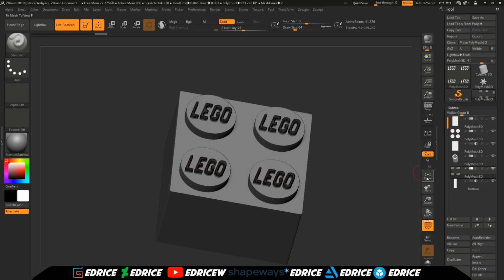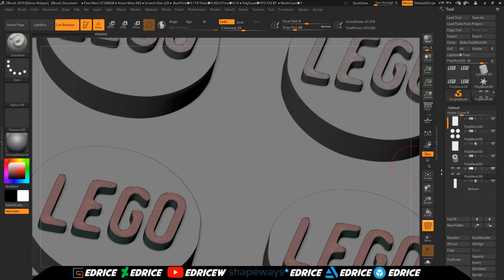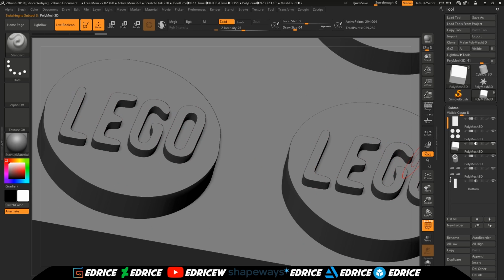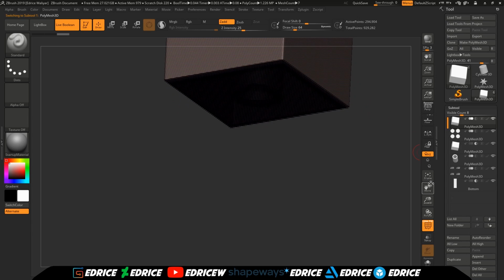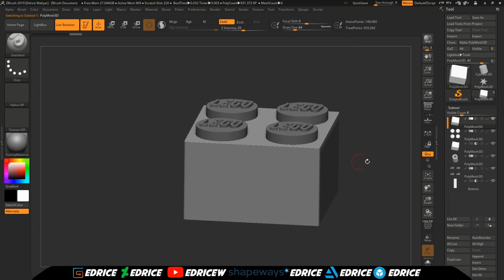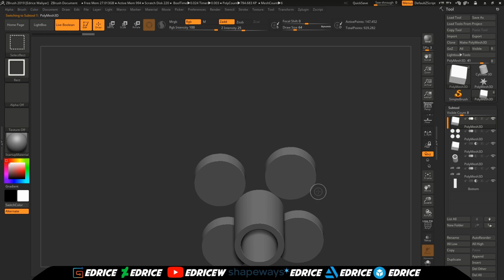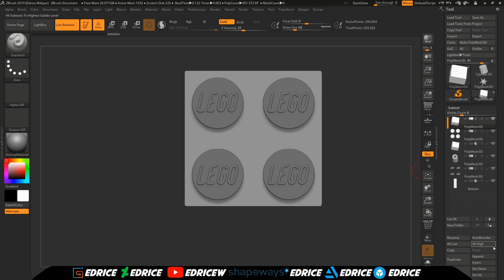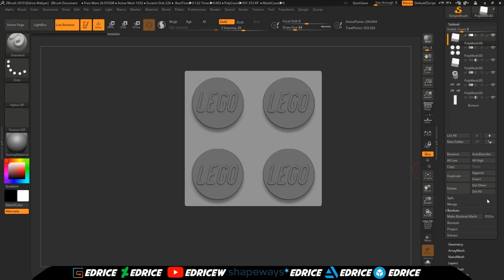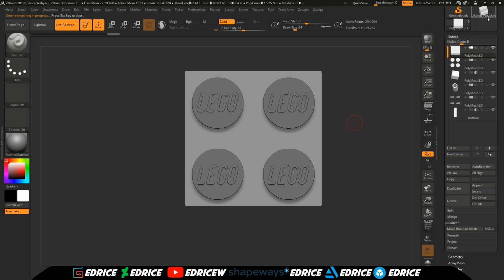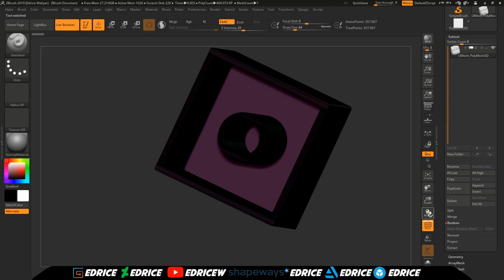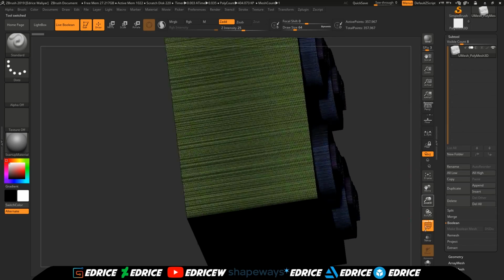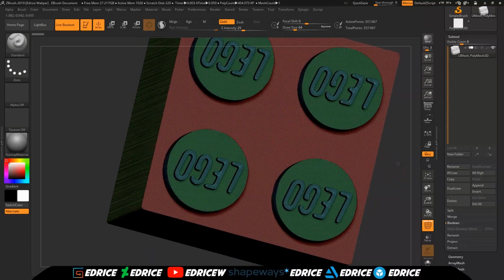Now, if you look at the polyframe for everything, it creates nice polygroups for every surface. So if you wanted, you could have nice clean polygroups for everything. Now you can hit Boolean, make Boolean mesh. Give it a minute. And now you have this nice Boolean mesh with not such a nice geometry, but with all the polygroups.